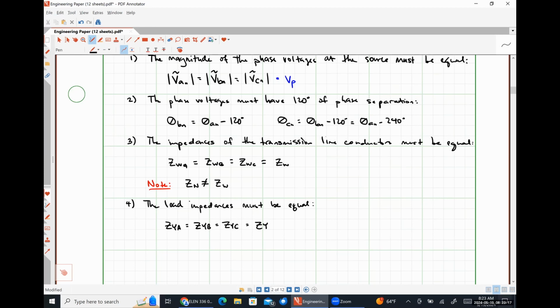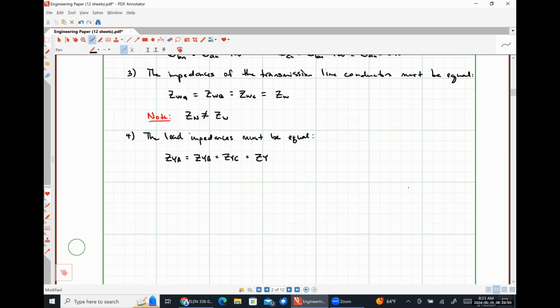And if I don't have a multiple of three buildings, it's going to be extremely close to being balanced, because I'm not putting all of those single phase motors on the A phase or the B phase or the C phase. If I spread them out as evenly as I can among the 3 phases, then I'm going to be much closer to a balanced load than if I had just thrown everything on one phase. You can do that with lighting loads and all of that kind of stuff as well. So that's just a pretty simple and common sense way to do it. If you have multiple of the same thing, just put one on each phase, and then it winds up being balanced or close to balanced the more you do it.